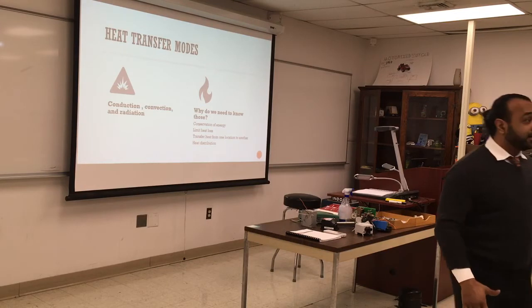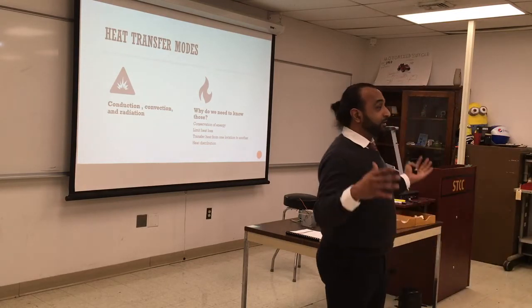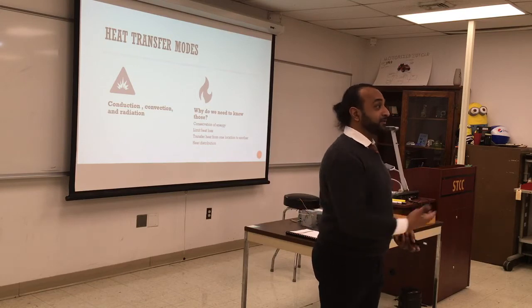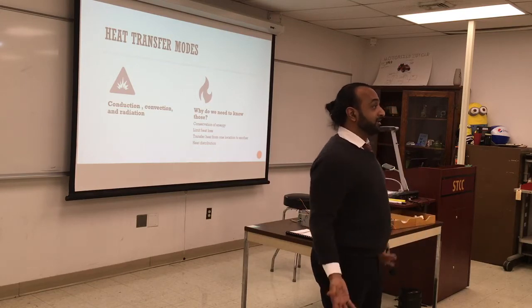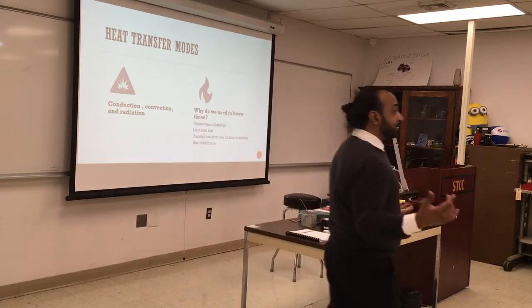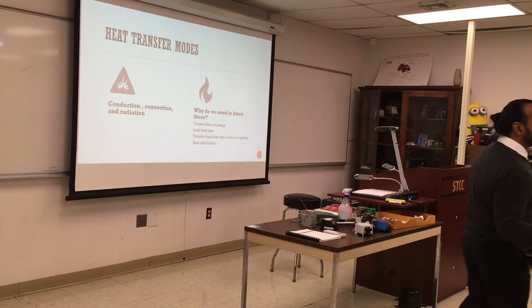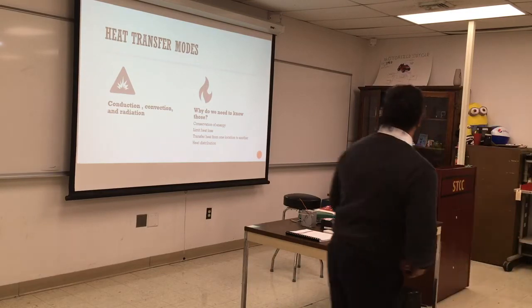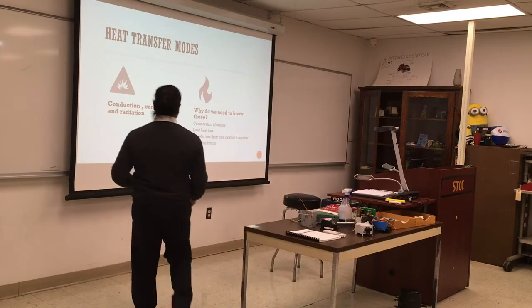It does not heat the air, it heats only the objects it hits. See how we are lit now? Same thing, the heat will hit us, and the air will not be affected. That's usually great for big warehouses and garages, where you don't want to heat the air. It's going to be a lot of air to heat, so it will save a lot of energy.